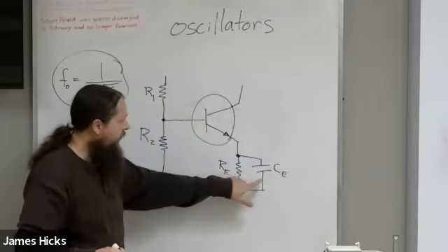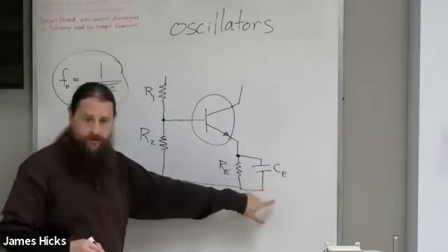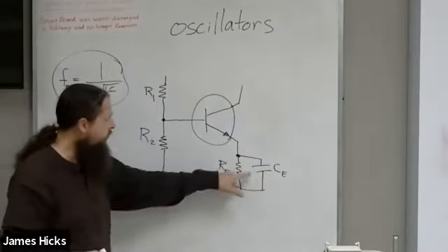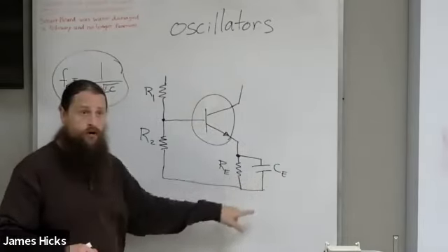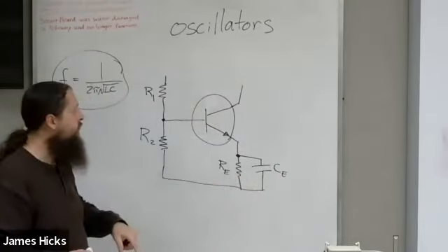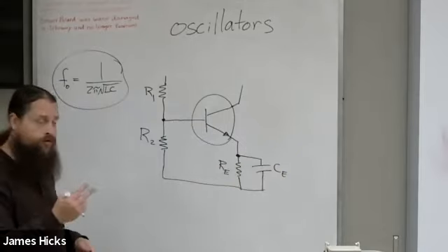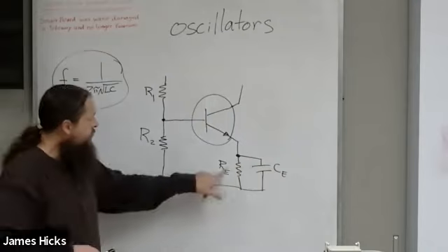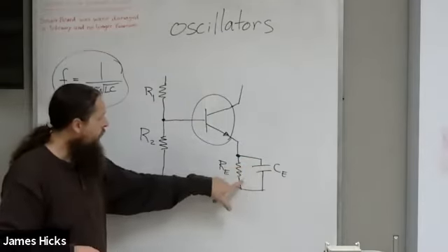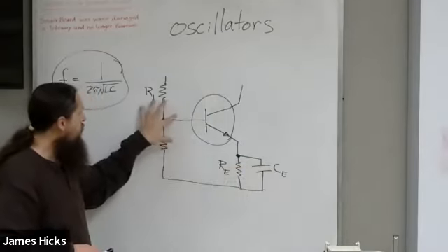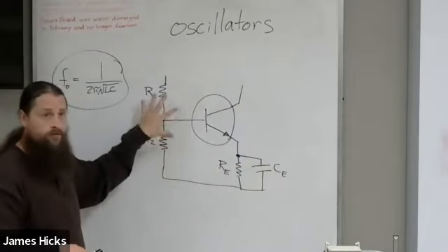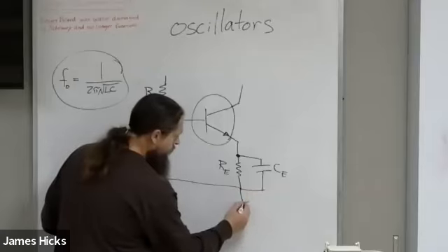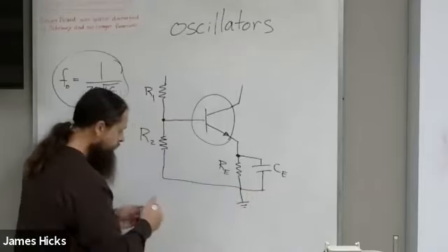And an emitter resistor and emitter capacitor, just like before. And the purpose of these, and the reason you see them on almost all transistor amplifiers, is for two basic reasons. Really, it's one. This pair helps to stabilize this base bias. This is typically our ground here.